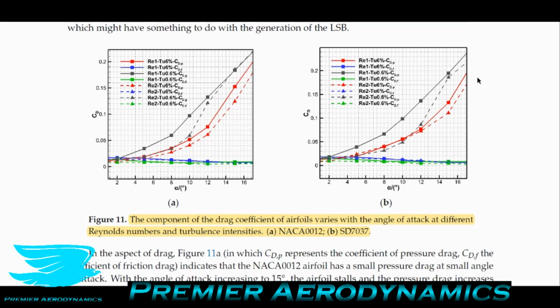There's also something called pressure drag, and this is the difference in pressure on the front side of an object to the back side of the object. So that difference creates a force, because pressure is just force over area. So that difference creates a difference in force, and then you get that resistive motion. You also can have something called induced drag. This is for airfoils mainly. So when you produce lift, you generally get something called induced drag, and this is characterized by vortices that are forming at the wing tips. Or there are some flow control devices. I'm not going to get into them in this podcast, but you can see vortices in different areas. They're generally speaking induced drag.